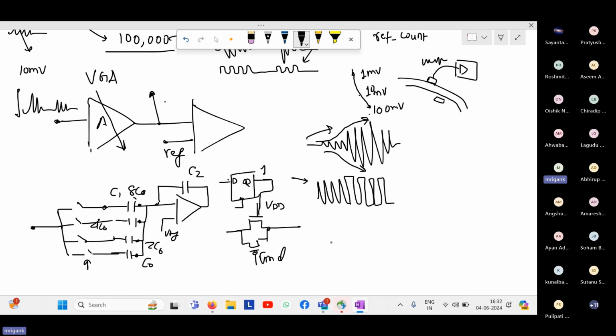So you will need, in this case, 4 flip flops, which are going to store the tuning bit, which are going to connect to these switches, which are going to decide whether the switch is going to be on or off. Likewise, in design, for many different modules, we require tuning options, and those tuning bits are generally stored in flip flops. So using your initial reset operation when you are loading your data in the circuit or in the chip, you will have this tuning option available.